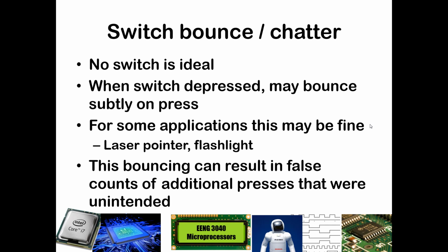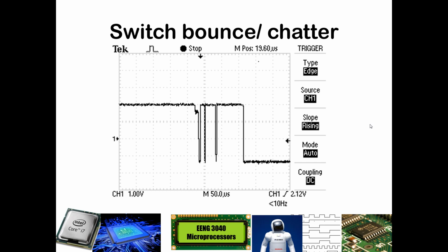You want to make sure if you push that button once, it in fact is registered as pushing once and is not registered as pushing multiple times. So in certain areas it will be very critical to do a switch debounce, and so we will introduce a schematic here that will help us to mitigate the effects of switch bounce.